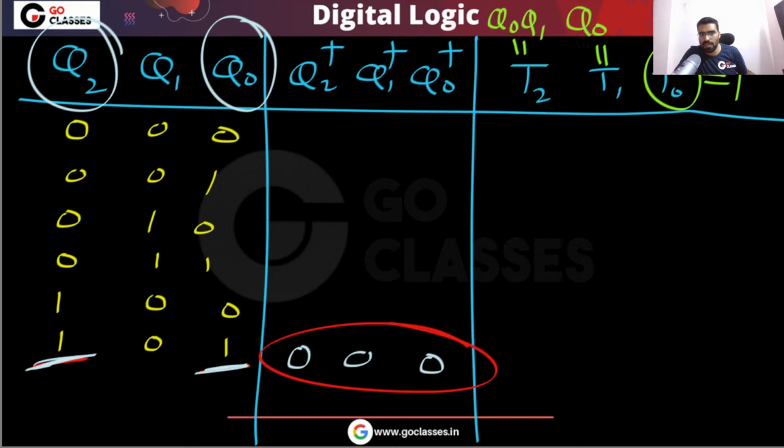In other situations, everything is fine. In this situation, the next state will become 0, 0, 0. If you take 1, 1, 0, then also it will become 0, 0, 0. If you take 1, 1, 1, then also it will become 0, 0, 0. So whenever Q2, Q0 is equal to 1, 1, the next state will become 0, 0, 0.